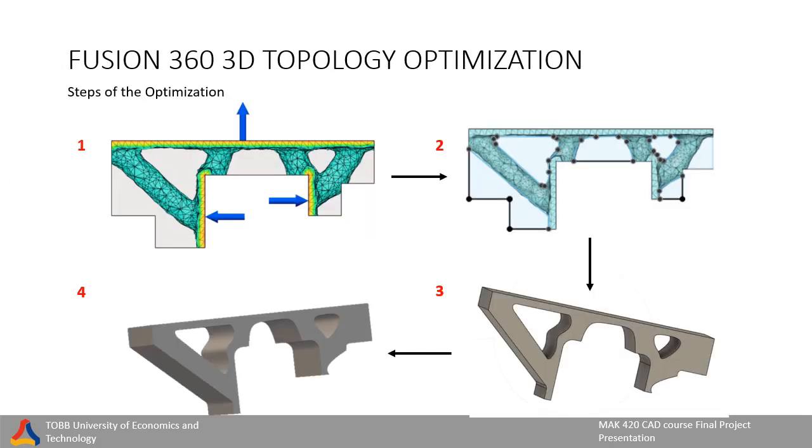After the determination of the design area and the selection of the material, the optimization steps are carried out. After the determination of the relevant forces and boundary conditions, the topology optimization is performed. The solid part, which reaches its final state by removing unnecessary parts from the result obtained at the end of the optimization, is finally converted into an STL model and brought into a producible form.